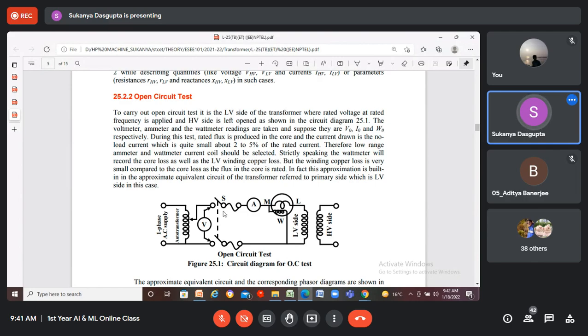That's why one ammeter is placed in series with this current coil to measure the supply current. And the pressure coil will have more turns because it carries the voltage of the circuit, and it is connected in parallel with the main supply. Here, this pressure coil is connected in parallel with the variac, or in parallel with the voltmeter, to measure the voltage of the circuit, right?